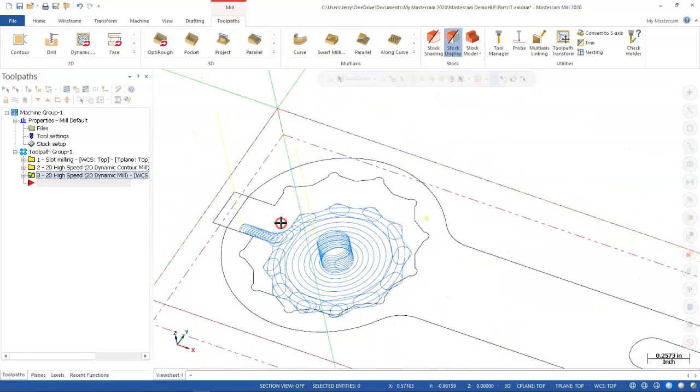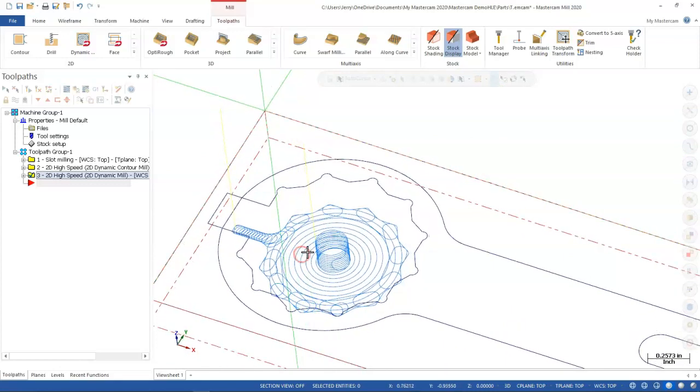We still have to account for that tool load, flushing the chips, the fact that it's steel. But that gets us a little bit closer. We could tighten up those step over amounts, reduce the engagement, and that would allow us to increase the feed. So you run a little bit faster. But again, it's still that balancing act of what's going to work best.